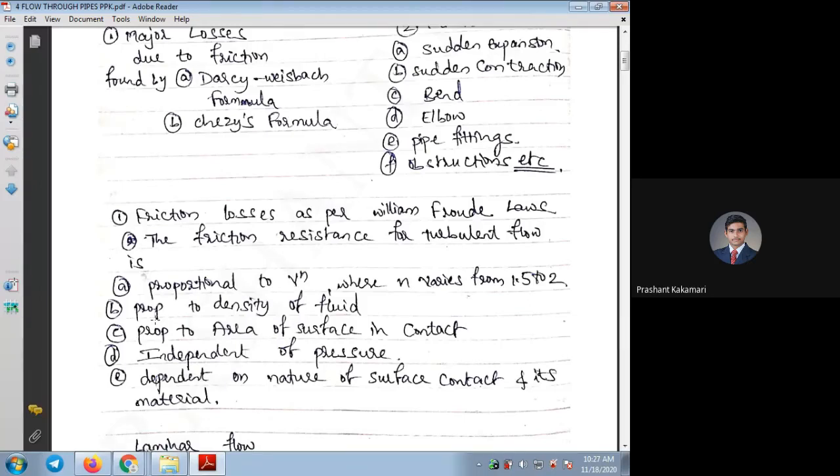So what will happen? The diameter of the pipe is also reduced a little bit, so the area will also reduce. So after long usage, even without changing the inner diameter, depending upon the depositions or the turbulent flows inside the pipe, the pipe surface may turn from roughness to smoothness. There also the frictional losses will be reduced. That is also one of the things.